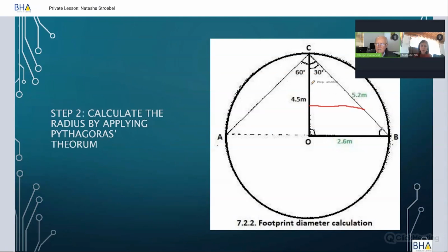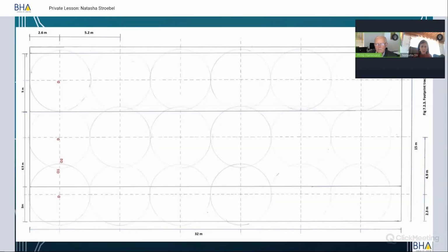You do your calculation again, and you see what lux you've got at this point. We know what the lux is underneath the light, so we know what it will be on our driveway. And then you calculate what it is there, and that's on your pump face. And once you've done all of that,